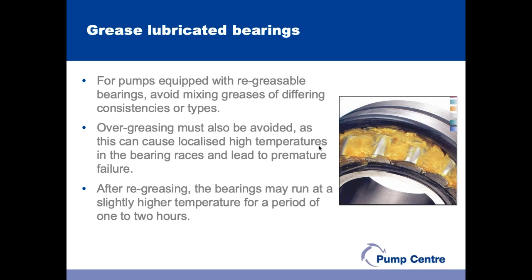bearings. Some of them are sealed for life, so they're sealed with lubricant within, and no re-lubrication is required. But for bearings where additional grease does need to be introduced, it's really important not to mix greases of different viscosities or different types. And once again, over lubrication is something that really doesn't do the bearings any good at all. It leads to high temperatures and can lead to premature failure of the bearings.